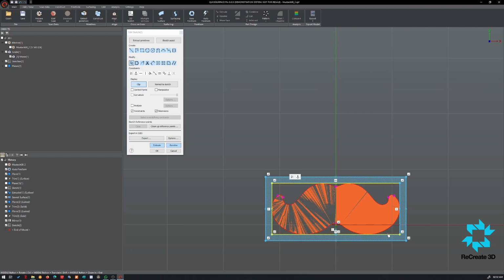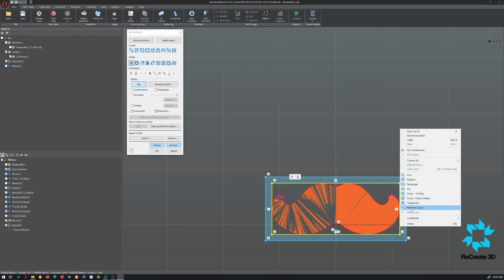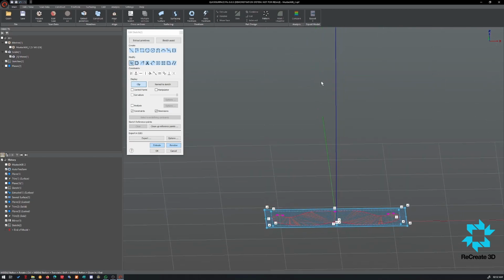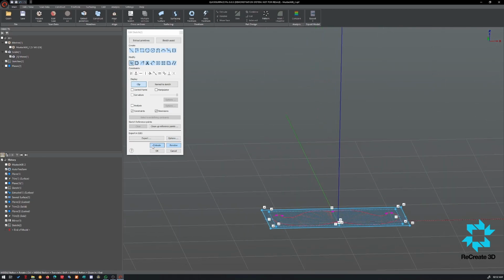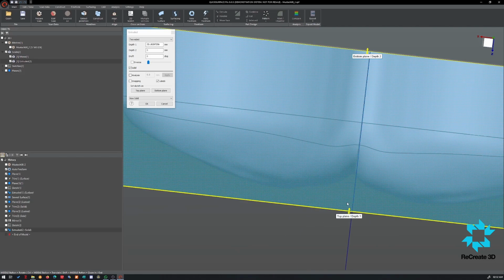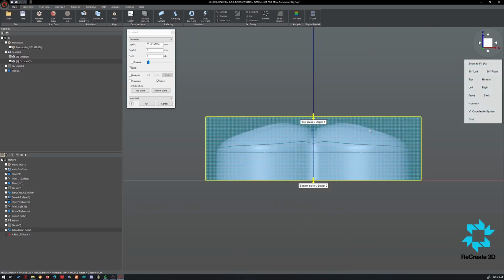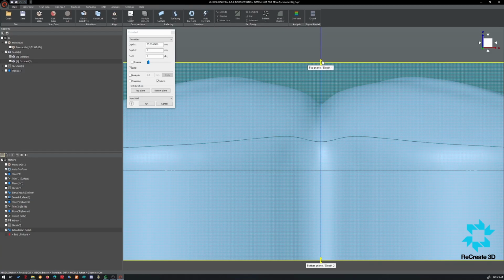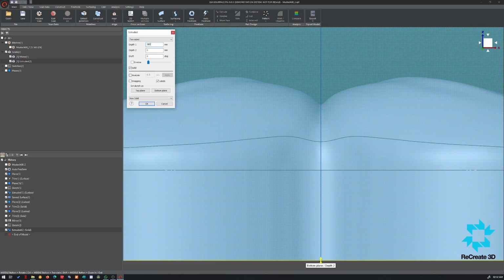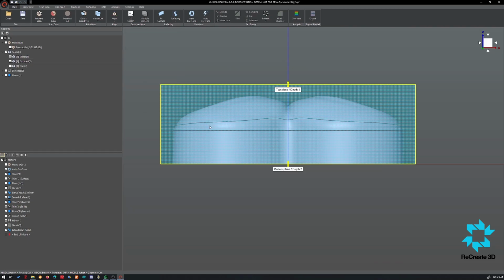Now we are going to make a construction, and then we're going to extrude. We can eyeball it a little bit. So top plane number 30, yeah, that's correct. So we'll just make it 35, 35. And as a new solid.